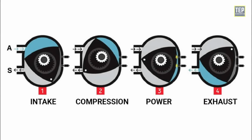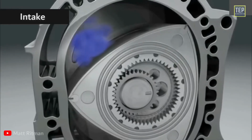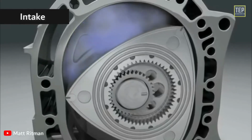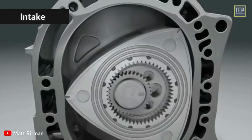Now let's go through each of the 4 strokes of the engine, looking at one face of the rotor. Starting with intake. As the rotor moves past the intake port, the volume of the chamber expands, drawing air or fuel mixture into the chamber. When the peak of the rotor passes the intake port, that chamber is sealed off and compression begins.